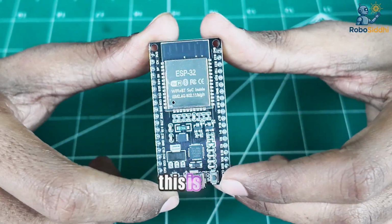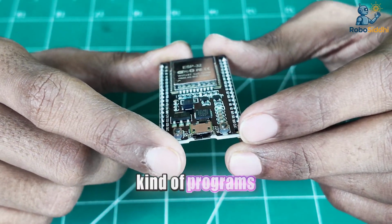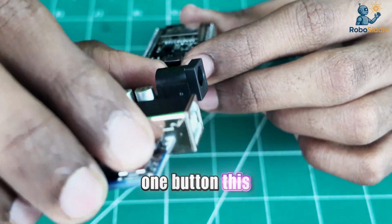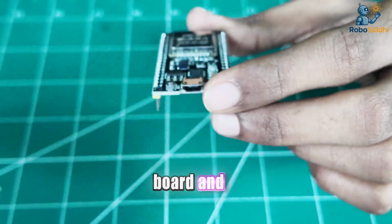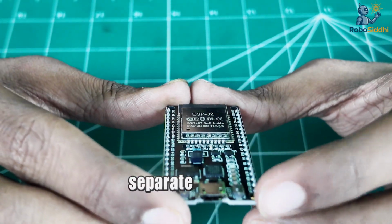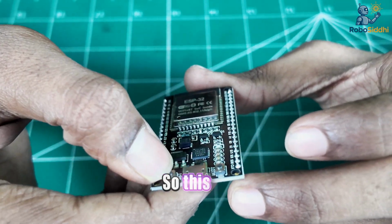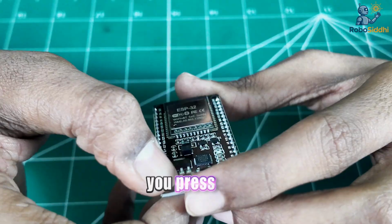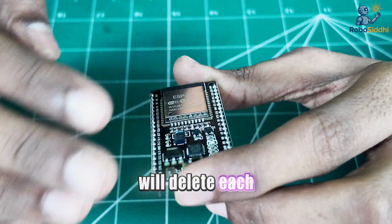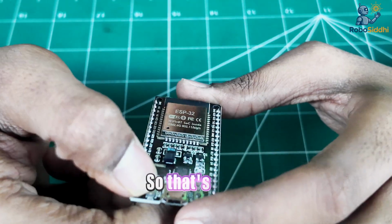Now if you see, this is how the board looks like, and the board is going to have a USB port to upload or flash any kind of programs in your board. Then you are going to have two buttons. In Arduino, we only had one button, this one, that will only reset the board and it will restart the program. But in our ESP32, there are two separate buttons or switches. First of all, one is called RST, which stands for reset. So this is for resetting the board, which means if you press this button, the ESP32 will restart, reboot, and it will delete each and every data that it has collected, and it will restart the loop again. So that's how it resets.